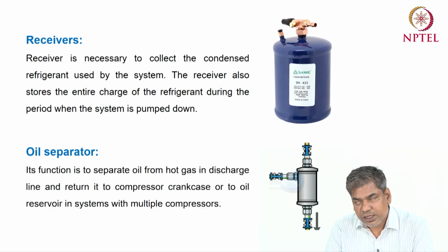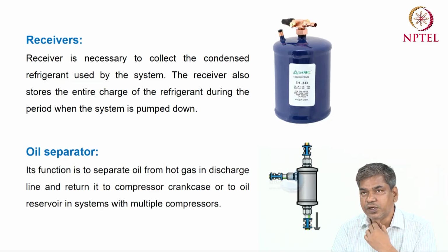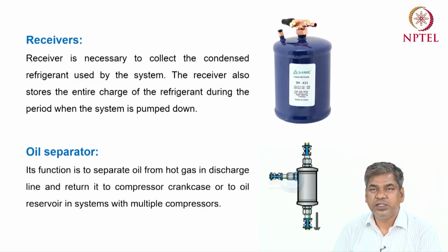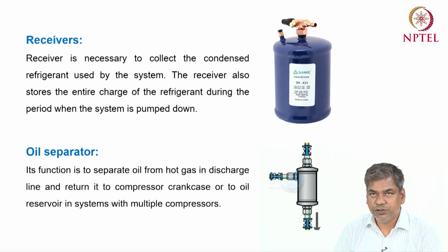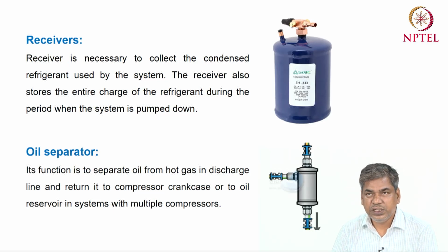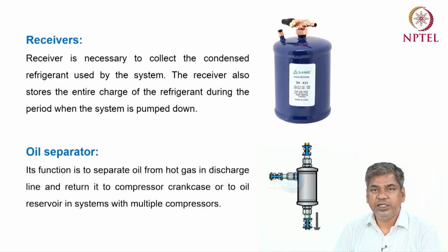Okay, so the receiver and the accumulator are both basically storage devices, but the accumulator can do another function also: we can confirm that the inlet of the compressor should always be vapor. So that condition is also confirmed by using the accumulator. Then there is an oil separator.